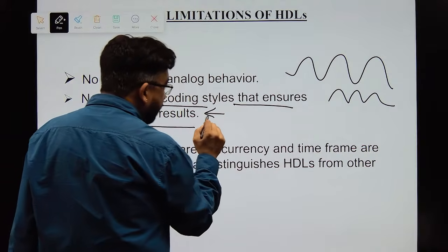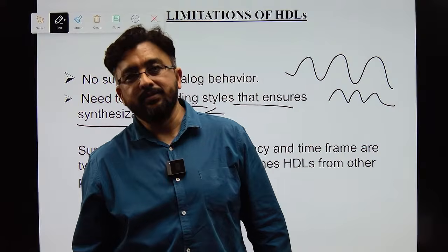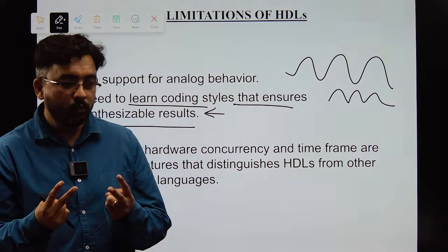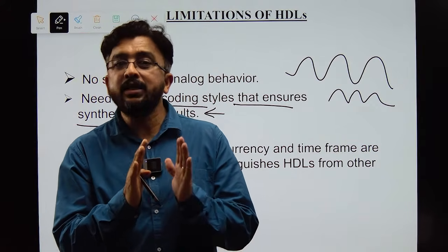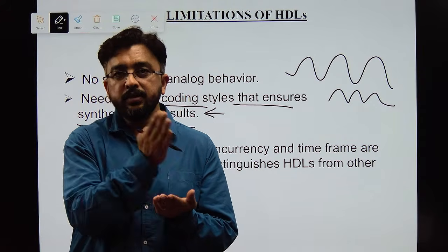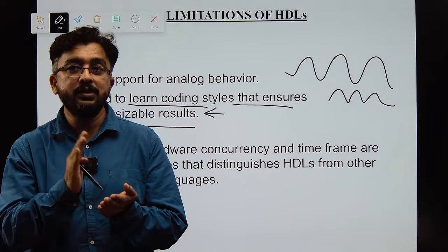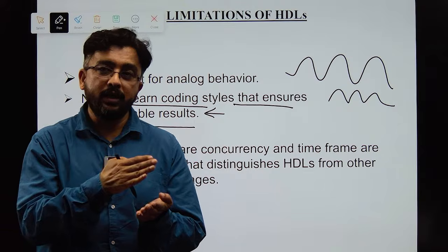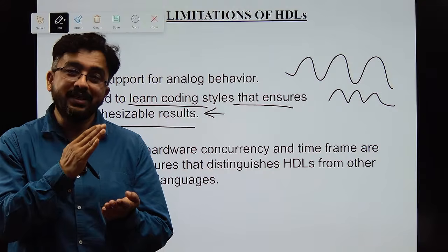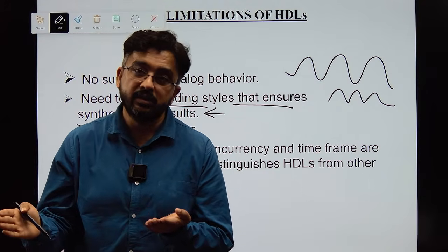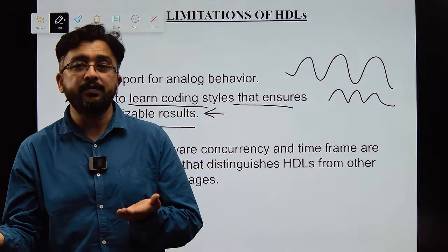Very important points. You cannot write anything. There are two types of syntax. One is synthesizable syntax, which generates the output from coding to hardware. That is called synthesizable syntax, or synthesis. There are a few syntax constructs which do not generate any hardware, which do not replicate into any gate-level hardware.